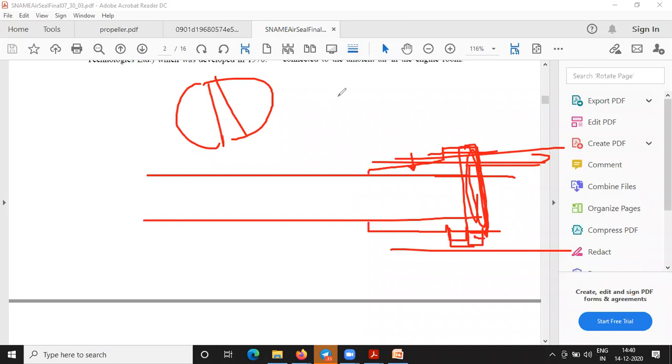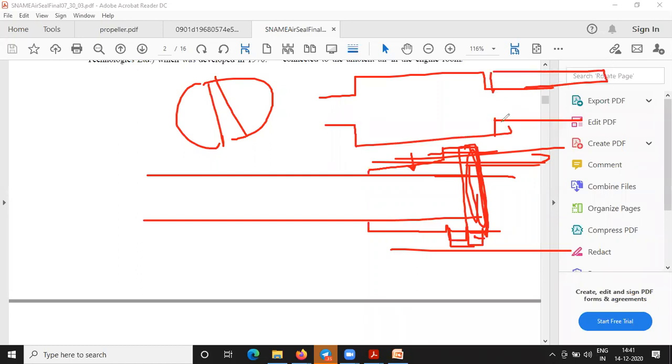So any sleeve also, even though you might have seen some of the pump shafts have a sleeve. So how do you fit the sleeve? You'll have to heat it and then insert it. Same thing you have to do here also. Okay. Okay, sir.